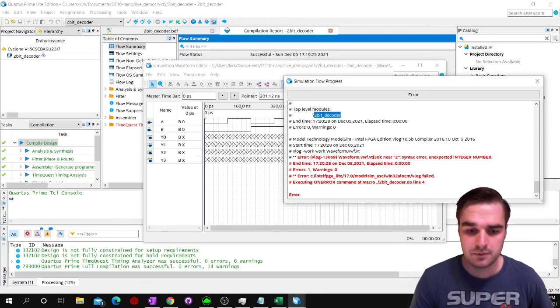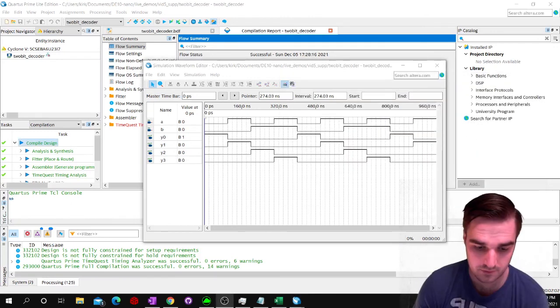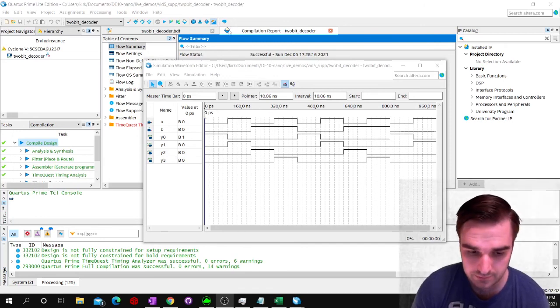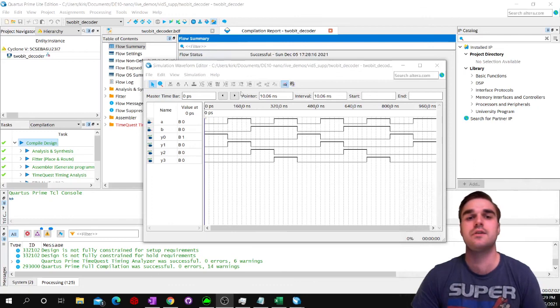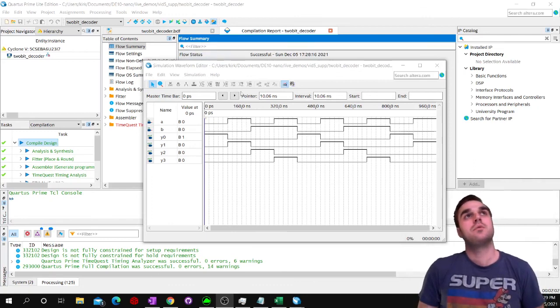Stand by 1 second. Okay, we are back. I just repeated everything I've done so far in this video, except this time I have named my project TWO bit decoder. So lesson learned, do not start your project names, your top level entities, or any of your modules with a number if you want to use the vector waveform.